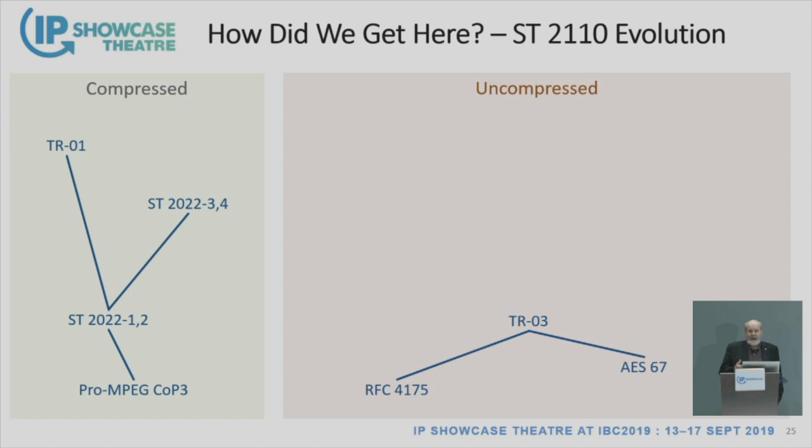In the meantime, we also had variable bitrate ST 2022-3 and -4. We had an uncompressed video signal that came out called ASPEN, also described in a SMPTE registered disclosure document number 37. That took uncompressed video, put it into transport stream, and used a lot of the transport mechanism in ST 2022. ST 2022-5 and -6, we were just talking about that. That's how we do uncompressed SDI, the entire payload, into a single packet stream. And a version of that was also developed called TR04.